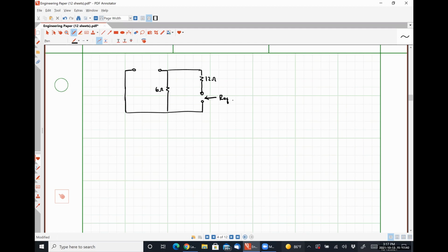So, what is the equivalent resistance or Thevenin resistance seen by this inductor? All right, so you're saying that it sees the 12 ohm resistor in series with a 6 ohm resistor, right? Okay, I agree with that. Step 5 will simply be plug our information into our generic equation. Then misspelling generic, excuse me.